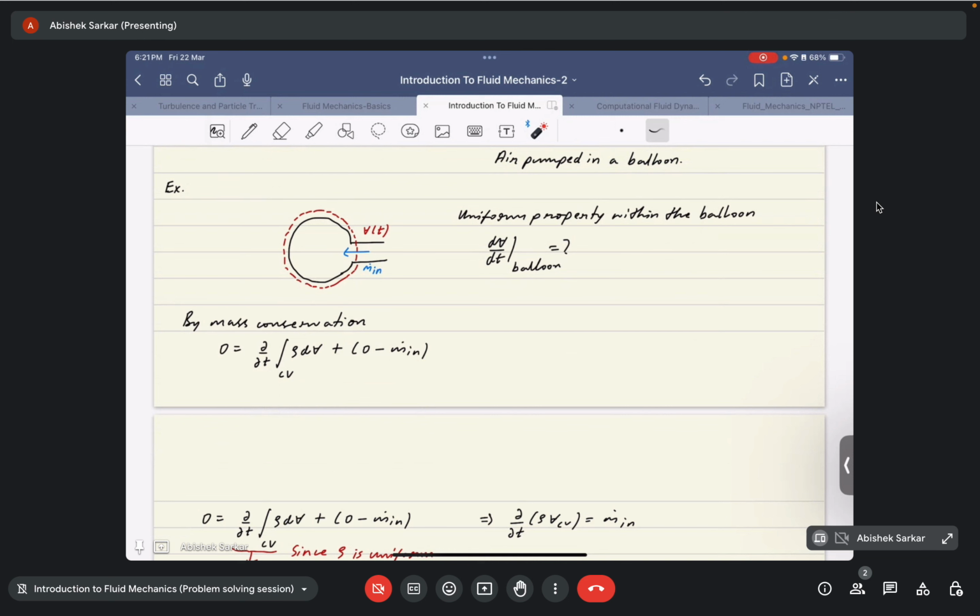Again, it may happen that for a particular problem we deal with a scenario where we are asked to find the net force or net drag acting on, say, a particular airfoil or flat plate. In those kinds of problems, since it deals with a net force that acts on the body, and force is basically the rate of change of linear momentum, we can say that a linear momentum conservation analysis would give us a proper insight into the problem, or into how the various parameters change in the flow.